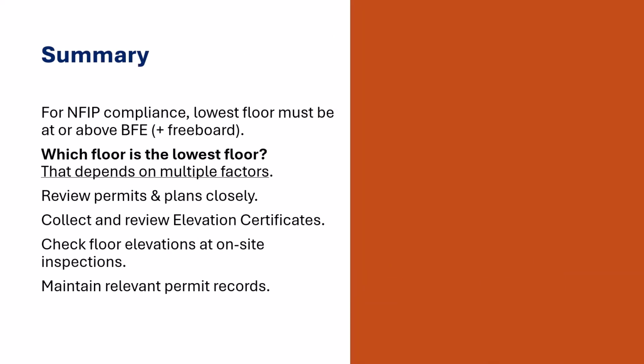We hope this presentation was a useful overview of how to understand what a building's lowest floor is for floodplain management compliance, and showing you that the lowest floor depends on multiple factors, so it's important to review permits and plans closely. Collect and review the information on elevation certificates to determine whether the building's lowest floor is the bottom floor, the next higher floor, the attached garage, or something different.